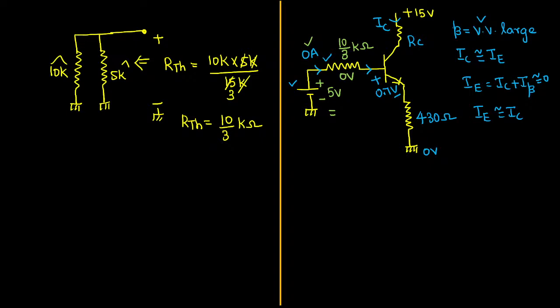Okay sir, that is not required now. Now can you please figure out the voltage across the emitter terminal? The current flowing through the emitter is called IE. For the 430 ohm resistor, current entering point plus, leaving point is minus. Then how will you write down the voltage drop? Okay, let me write. The voltage drop can be written as V is equal to I into R. Emitter current I into 430 ohm resistor. That is how we are writing the voltage drop for the emitter.